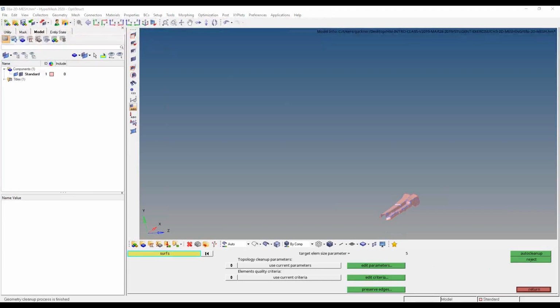The fact that you guys are drawing up your CAD, if you find yourselves having way too many surface lines that's making meshing hard, well, the easiest answer at that point is frankly just go back into your CATIA file or your SolidWorks drawing file and adjust the surface definition within the CAD tool itself. And that's one of the luxuries that I think you guys have as well.